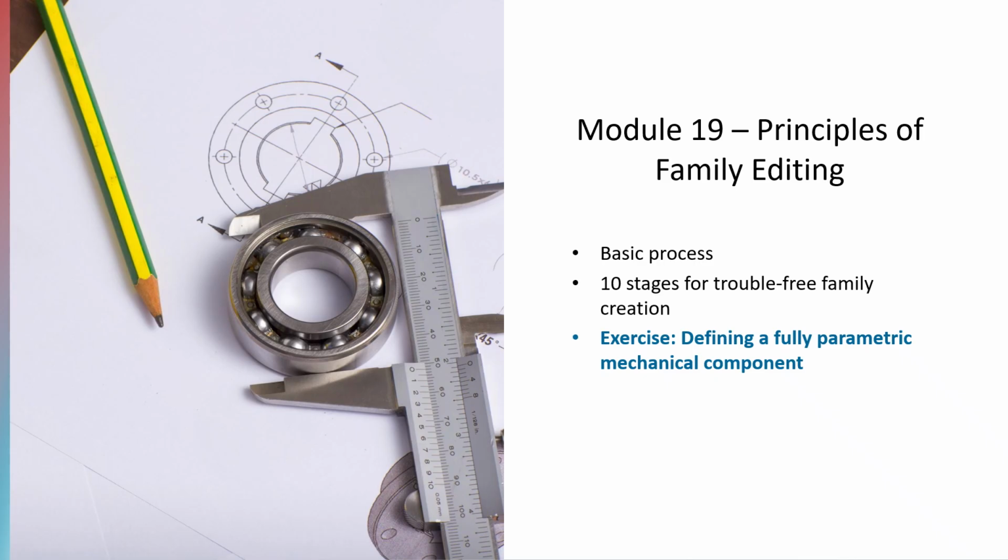In this module, we focus on the art and science of creating custom Revit families, components that are intelligent, parametric, and reusable. We begin with the basic process of family creation. This includes choosing the right template, defining reference planes, and setting up parameters that drive geometry and behavior. Then we walk through the 10 stages for trouble-free family creation.